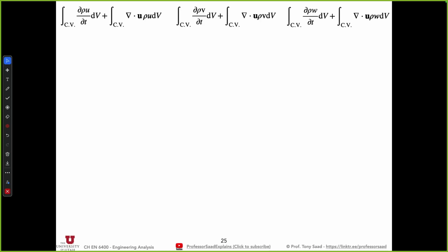Next, I want to talk about the advective fluxes. This quantity: u rho u, u rho v, and u rho w. I come from a school of thought where it's very important that I write it this way. Because I know when you expand the terms, you can rearrange them. I don't rearrange them because I want to be unapologetically unambiguous about what is being advected and what is advecting. These animations took me about three hours to make.